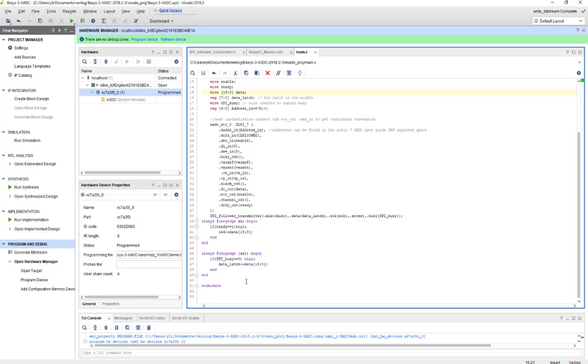So I can use other signals to synchronize the communication of the SPI on the two sides, so I don't have to worry about the clock of the XADC. So I still keep the 100 megahertz clock for the XADC, but change all the other signals to update the SPI's signal lines. Those are the efforts I made, and it didn't help. I didn't even change the results. I didn't see any differences. So let's just come back to Taylor's methods.